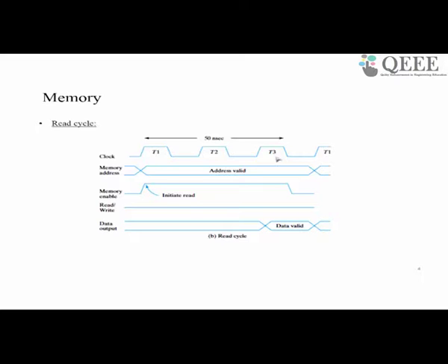In terms of the basic clock, at various clock periods, how the signals change and what operations get carried out. Normally we refer to these clock periods as T states when it comes to the processor. So we will distinguish them as T1, T2, T3. For the present, let us assume that it takes 3 clock periods for this read cycle to go on.